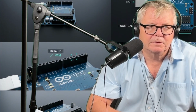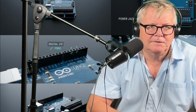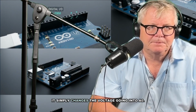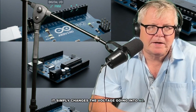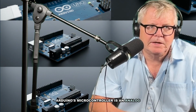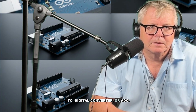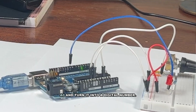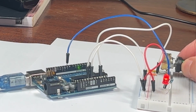As I turn the knob, the voltage on A0 changes continuously between 0 and 5 volts. That is an analog signal. The potentiometer itself does not convert analog into digital. It simply changes the voltage going into A0. The ADC inside the Arduino's microcontroller is an analog to digital converter. Its job is to take the analog voltage on A0 and turn it into a digital number.